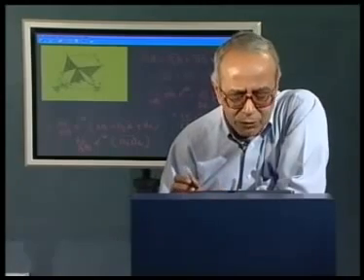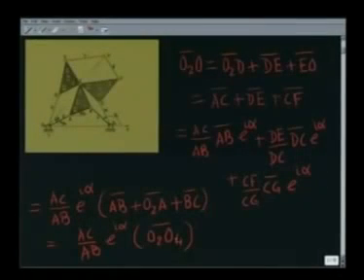As the mechanism moves, all the vectors change, but O2O4 never changes, because O2 is a fixed point and O4 is a fixed point. So, the vector O2O4 is always on our x axis without changing its length. Neither the length AC nor the length AB changes, because those are the rigid link lengths. Same is true for this angle alpha, which is again the angle alpha of this ternary link. Consequently, as the linkage moves, the vector O2O never changes, which means the point O never moves in this mechanism.